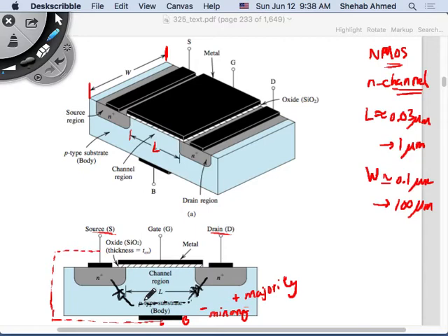You have to overcome the depletion layer voltage. So how do you do that? By making this barrier voltage smaller by adding an external forward voltage. Here, I'm not going to add an external forward voltage. So is this diode forward biased? Reverse biased. There's no current that will flow in this diode.